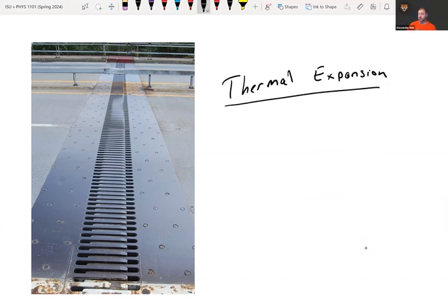The idea is that the materials the road is made out of are going to have to compensate for a variety of temperatures, which means they're going to expand and contract. Basically, what this joint does is lock it together in this comb shape, so that when it expands it has room to move, but it also has room to contract without the road slipping apart into different pieces. When it contracts, you don't want the pieces of the road to fall apart.